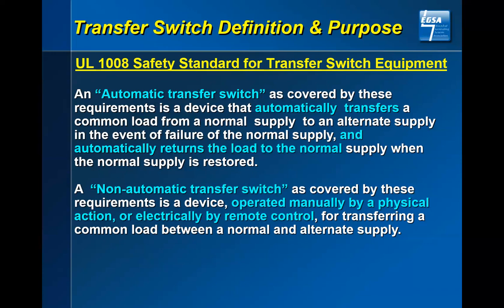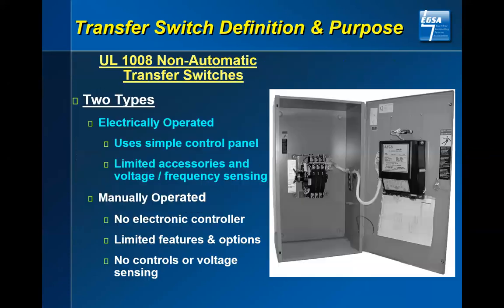When you look at a non-automatic switch, the power goes out, and someone has to go and initiate the transfer over to the other side. And then when it comes back, you have to reinitiate the power back. Why? Well, you may be in the process of doing something, and the utility is back, but you want to wait for that process to run, or a change of shift, before you do the retransfer back to your normal power. So when we look at a transfer switch, I'm going to state this now, what you are looking at is a typical ASCO product.